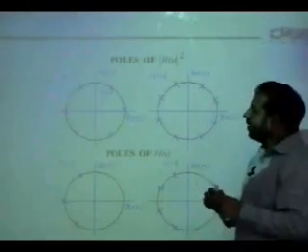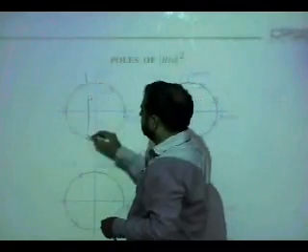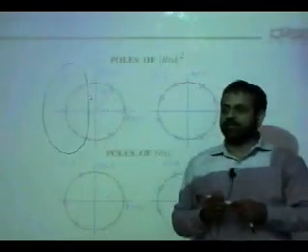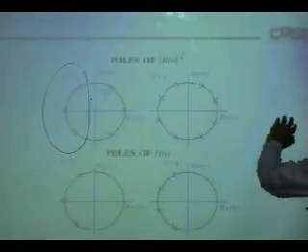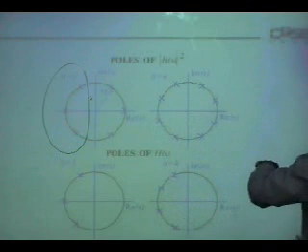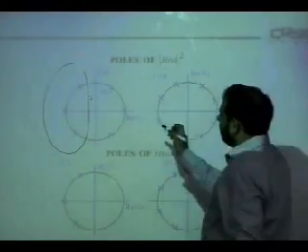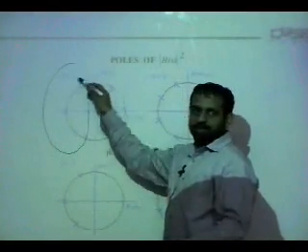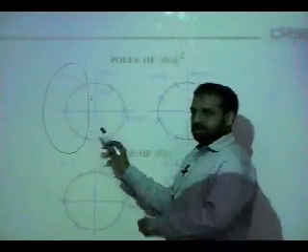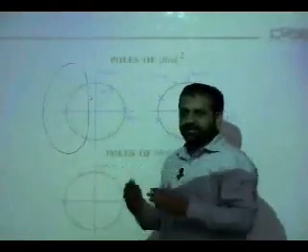So these are the 6 roots. I always pick these because the left half of the s-plane means a stable system. So I always pick these for h of s and I leave these for h of minus s. I always pick the ones on the left-hand side because I have to distribute them.